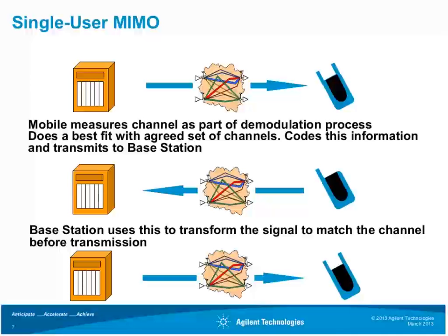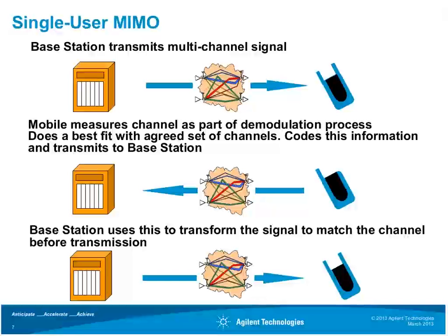Let me define pre-coding just a little bit more here. So the process of pre-coding the signals before transmission is to adapt those signals to the channel propagation conditions that the receiver sees. Important concept for MIMO. The signals are modified in amplitude and phase, and additionally cross-coupled between the antennas. So pre-coding is used to equalize the performance of the two streams of data.